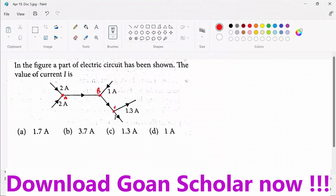Let's first deal with junction A. So what is our junction rule? Our junction rule says that the current entering the junction, 2 plus 2, must be equal to the current leaving the junction, which is from A to B. So let's call it X. X is the current going from A to B, so it must be 4 ampere. I hope this is clear.